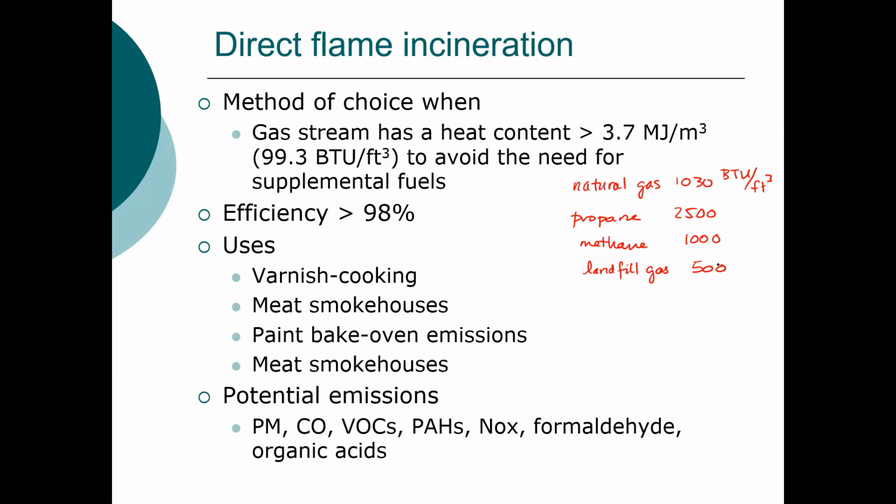Efficiencies are typically about 98% or more, and it can be used for a number of processes. For instance, varnish cooking, meat smokehouse, paint, and bake oven emissions. These contain significant VOCs. Meat smokehouses contain particulates, but they will also contain a significant amount of VOCs.